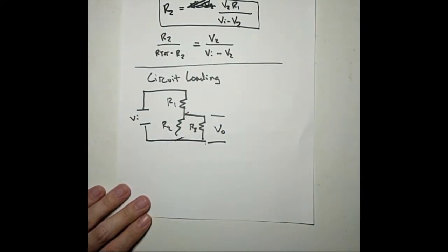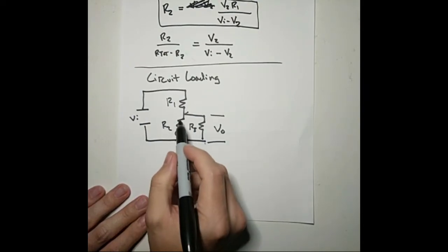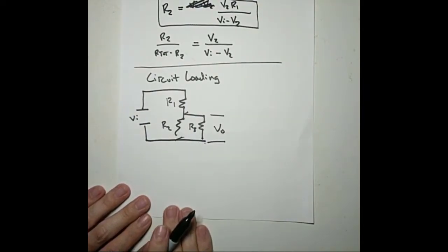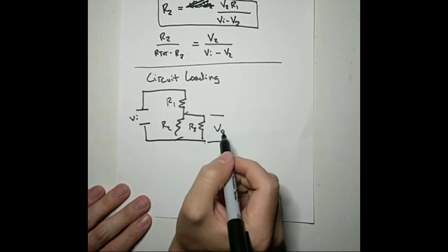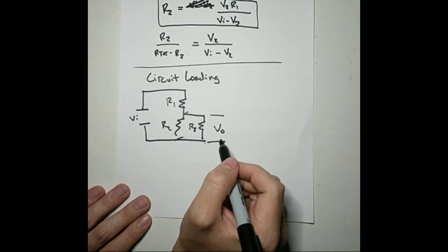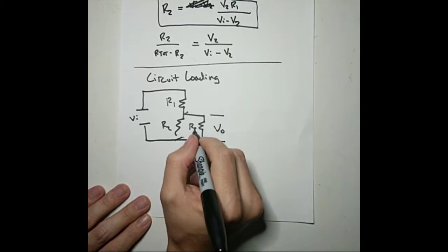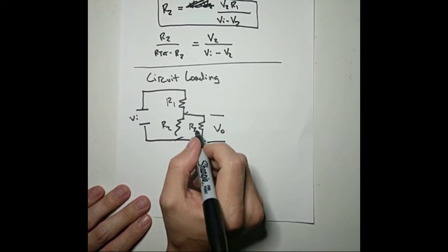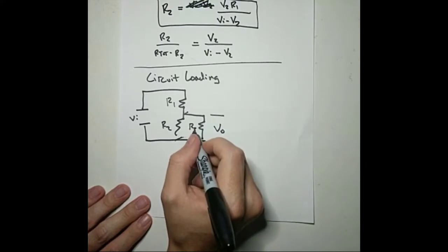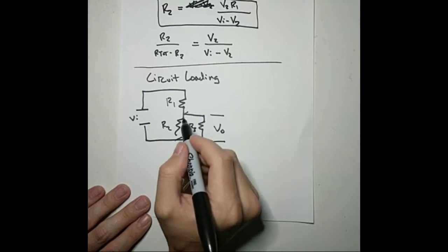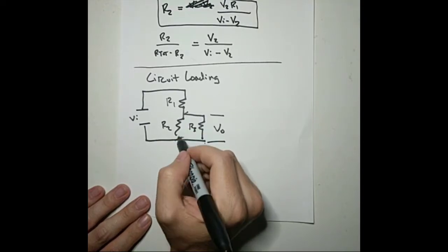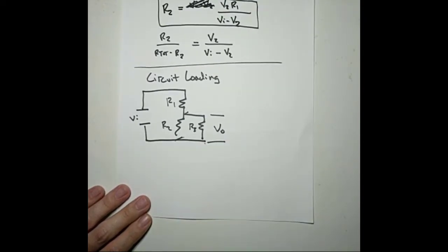So you've added a resistor in there. So just by trying to measure the voltage drop, you're going to introduce some error and change what that voltage drop across that element is. So one of the things we do in this lab is we calculate what the internal resistance of a multimeter is, and then we try to find what error is introduced for different values of R2 if we tried to measure that.